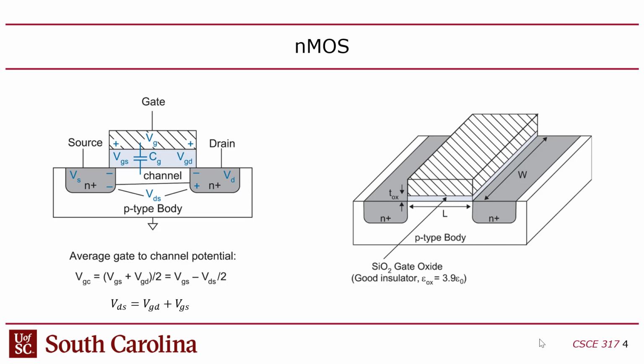It used to be metal. I don't know if you guys know, this is called a MOSFET, metal oxide semiconductor field effect transistor. So the MOS referred to metal oxide semiconductor, right? Except that's not metal anymore. They use poly for that now. Metal was the original way they built these. So now it's polysilicon oxide semiconductor, but they still call it a MOSFET.